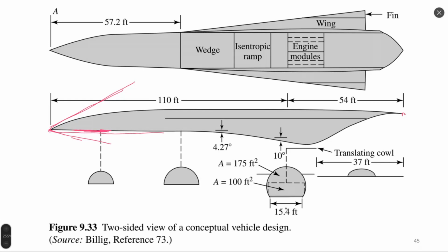Such a boundary layer creates, let's say, some sort of artificial wall, and the compression of flow happens due to existence of the boundary layer, because flow velocity inside the boundary layer is smaller, so we need to have more space because some space is occupied by the boundary layer. And due to this decrease of flow area with the rise of boundary layer thickness, we have a very weak, but still we have a shock wave.